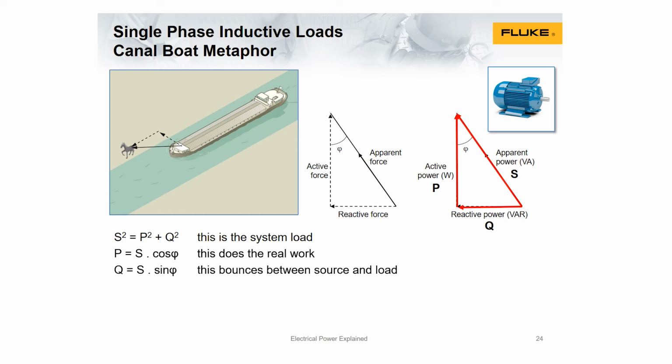You can summarize the performance of your whole system by the power factor PF. PF equals P divided by S, and PF equals cosine phi. The power factor is your primary performance indicator. It is cosine phi which gives the relation between active and apparent power. A power factor of 0 means that the current is lagging, or leading the voltage by 90 degrees, while a power factor of 1 means the current and voltage are in phase. So the smaller the angle phi, the closer is PF to 1 and the more effective your system.